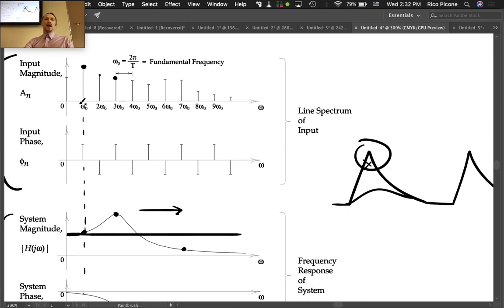Now we've got out here, because anything that's higher than this is probably getting smaller and smaller and smaller in the line spectrum, okay? So make it flat up to, say, here, then let yourself have that hump and that roll off, which you can do by increasing the natural frequency of the device, for instance. It's one way to do it.